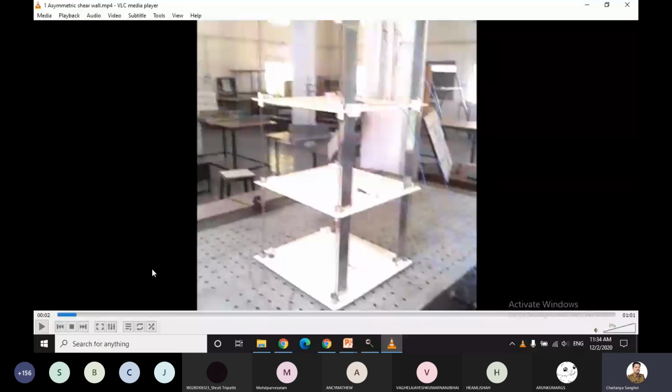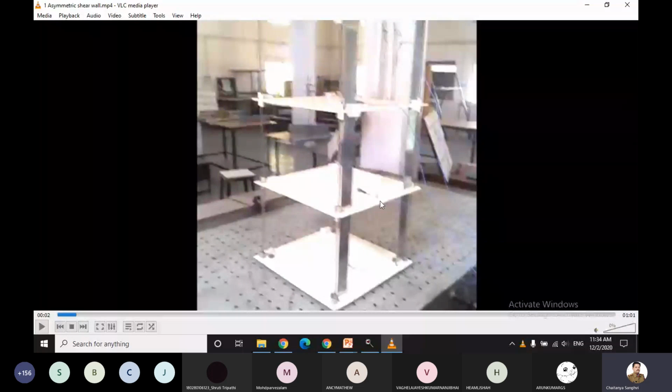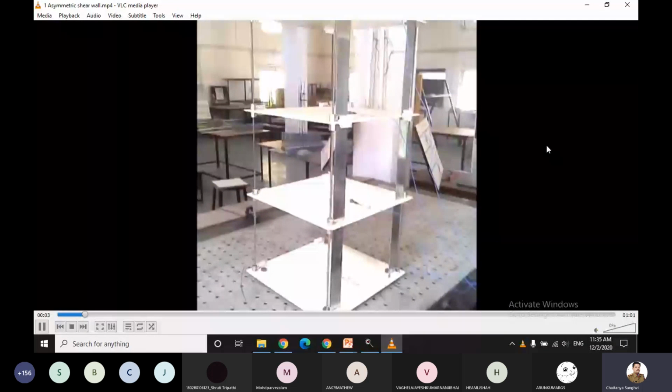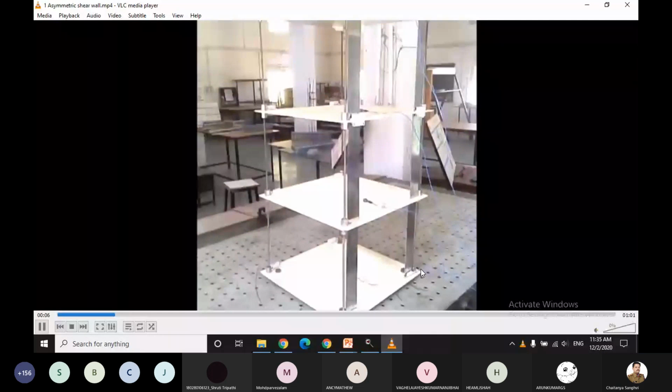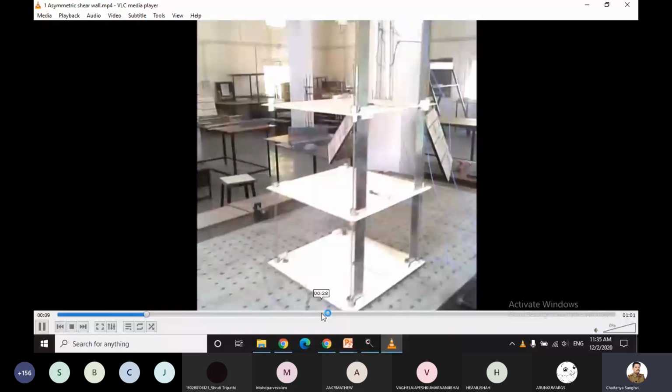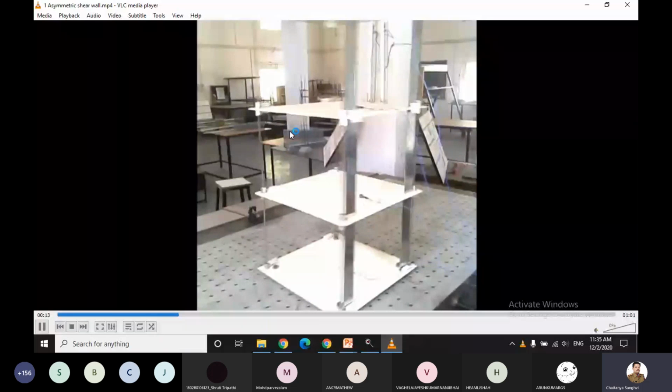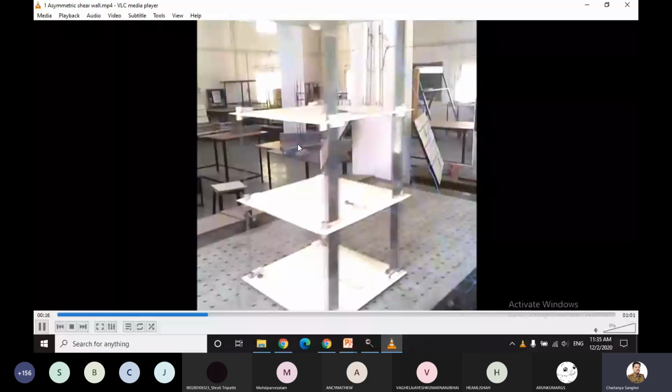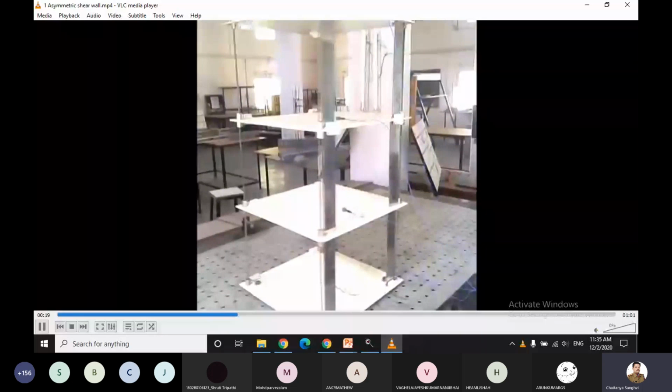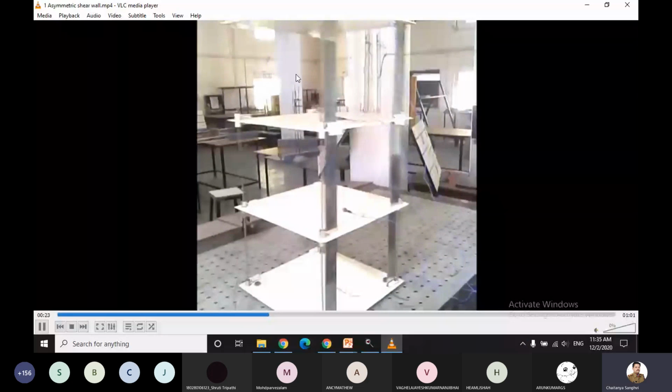Now here we have placed a shear wall, these steel plates, on one side, not on the other side. Now what is going to happen, you see, this is an asymmetric shear wall. What will happen? Look at this. Torsion is introduced. You can see the torsion in your building, right? So sometimes we place the shear wall on the back side and we make that part stiff. So this part is very stiff and this is very flexible. So torsion is going to come into the picture, right?